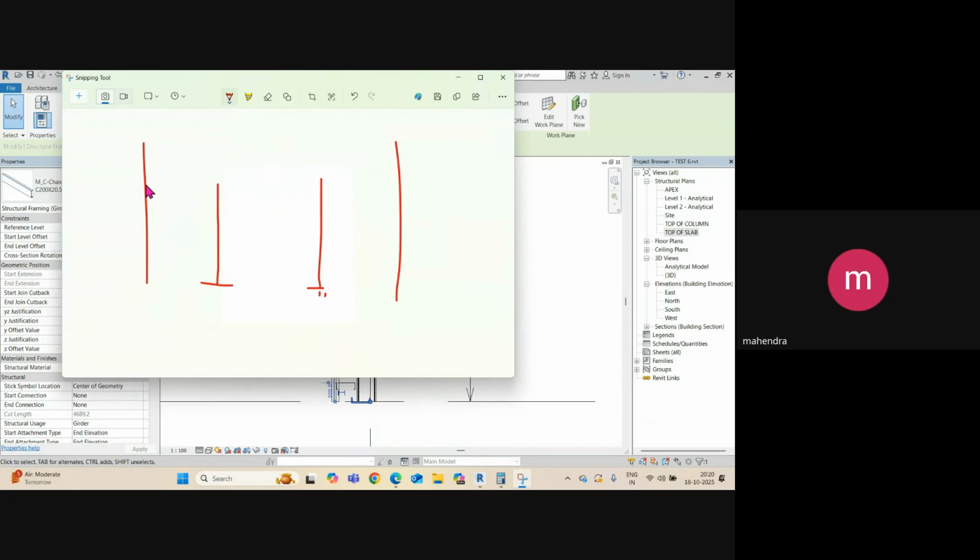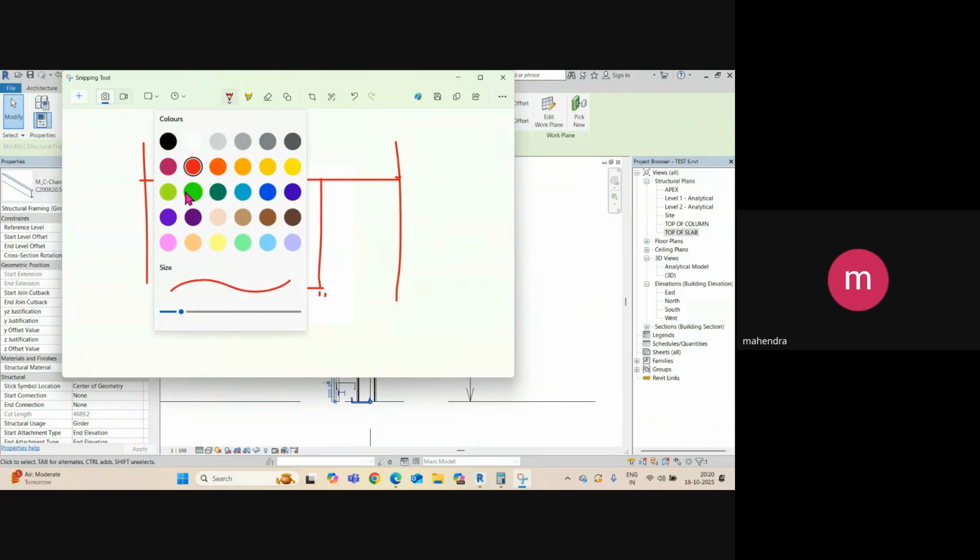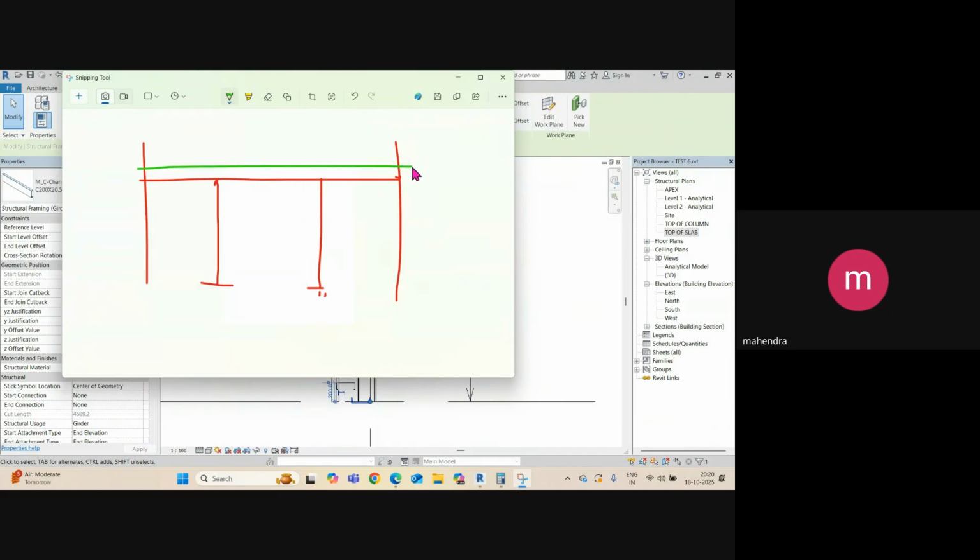This beam is connected to this by plate connection, and here also plate connection, or you can give the fully welded frame, from this one up to this one, right? And you can just assemble on site, or you can give one member separate with plate connection here and here, and here also you can give the plate connection, right?